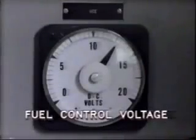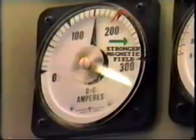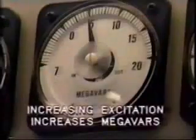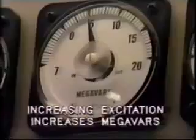In order to further increase power output, it is necessary to add more torque to the unit. This is done by increasing the fuel input to the gas turbine. But can we not also increase power output by increasing excitation? The answer is a definite no. Increasing the excitation will only increase voltage to a certain extent and will also increase the reactive power output of the generator. We'll be talking about this later.